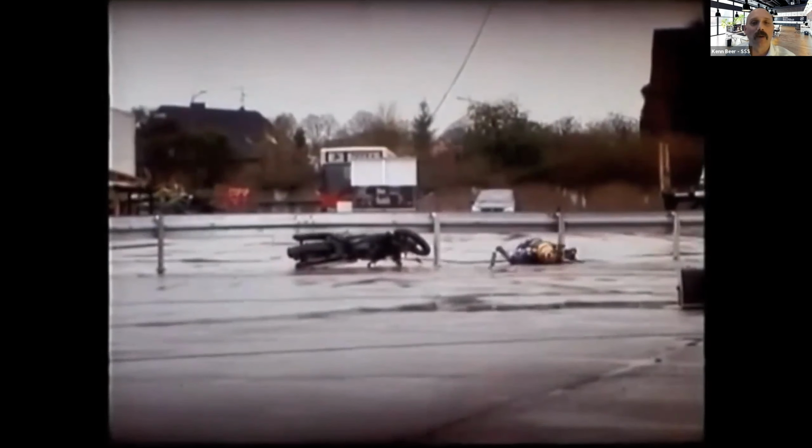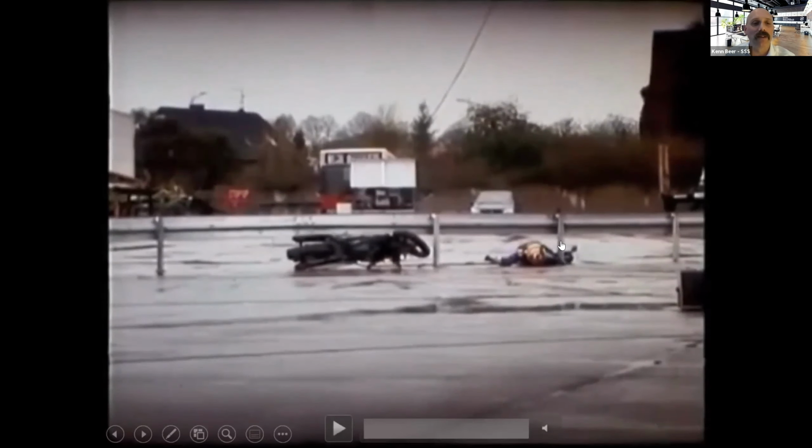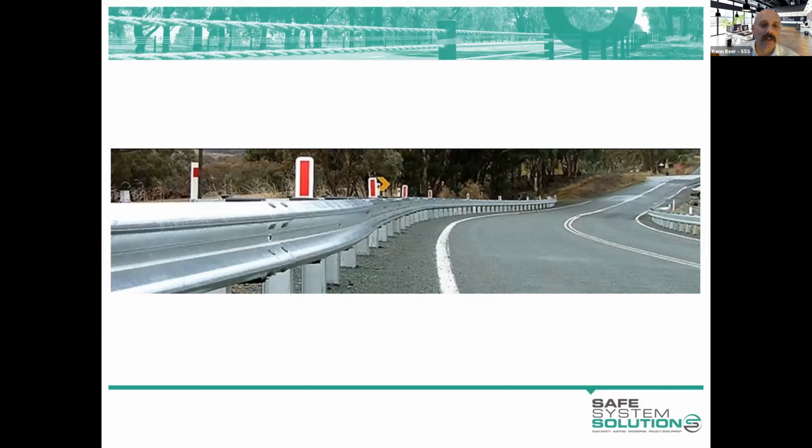If you have a perception that potentially the bike may do some protecting of the rider somehow, it seems to be in some modeling and some other things that shows that the rider is going to separate from the bike and most likely find a post. So another crash test dummy there. And you can see there that that's a weak post system. That didn't really budge when the weight of the human body hit it. Breaks off with the weight of the bike, one of them, and obviously with cars. But the strength of the weak post systems is certainly enough to kill a motorcyclist.